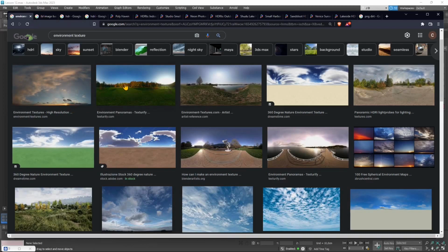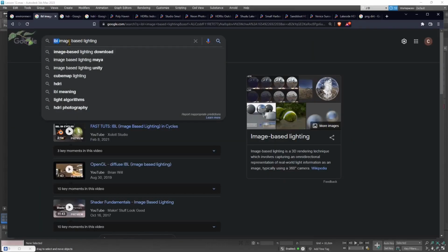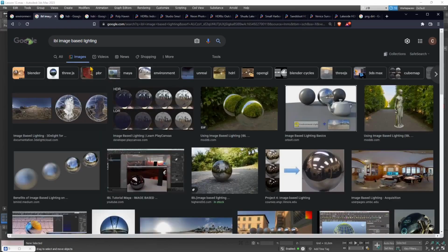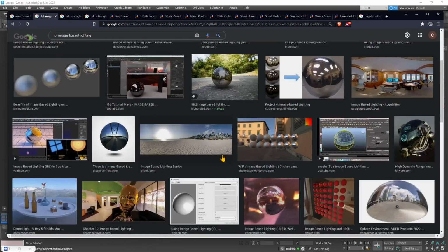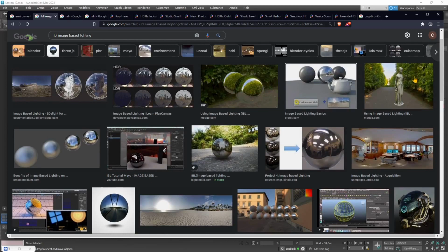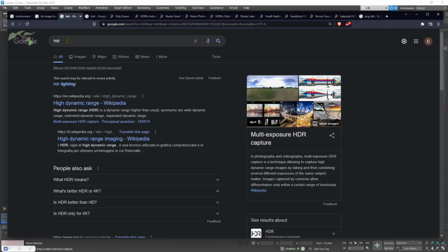So it's gonna help us to create quickly a context, a scenario for our scene without the need to model the entire scene. We're just gonna need an image. Now this technique is called IBL, image-based lighting. So it means that I'm gonna use an image to have the background there and also to illuminate the scene from every direction. It works similarly to the dome light that we saw before. In fact, you can use an HDRI also with a dome light. So it's gonna illuminate coming from every direction towards the center of our scene, which is probably the position of our subject.